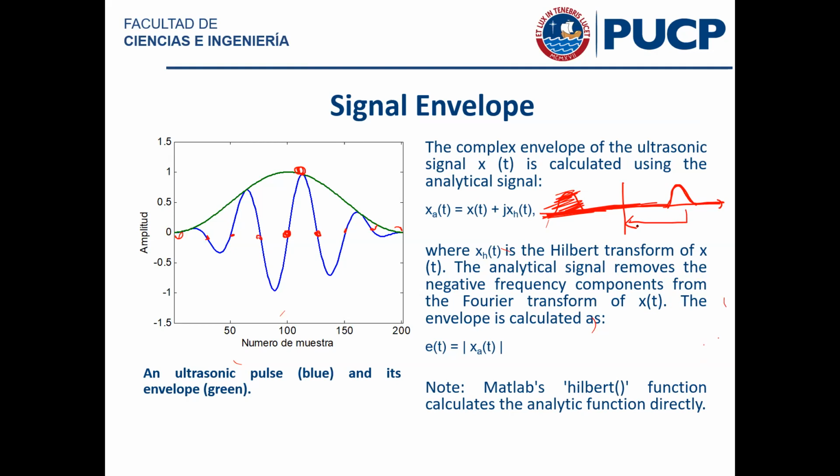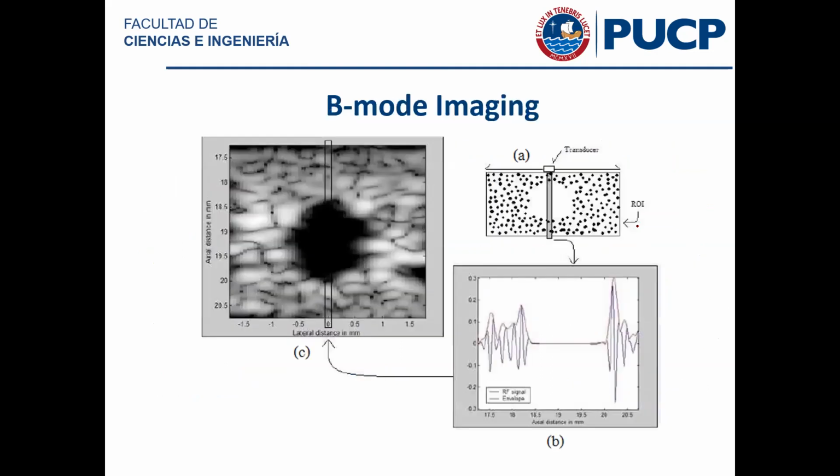You can do that with IQ demodulation, which you have probably heard of before, which involves multiplying the real signal with sines and cosines and mixing them accordingly. Maybe you have read about this. If you have not, then you can look it up. Bottom line is you care about finding that green signal, because it will tell you how strong the echo is, without the nuance of those nulls and peaks that would produce oscillations in your resulting image.